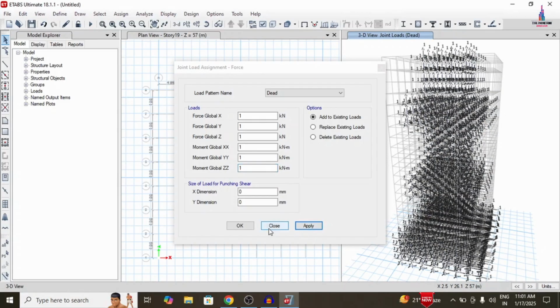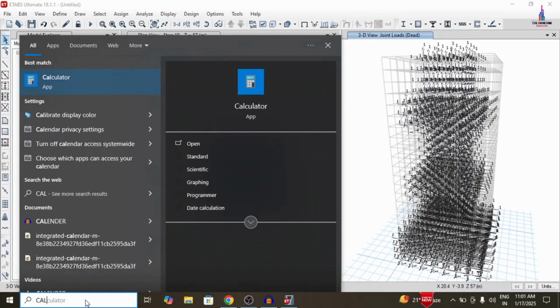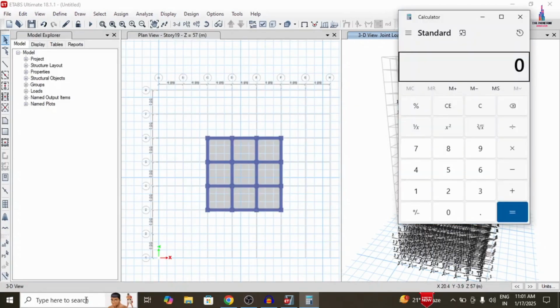Now after this we have to apply the wall loading condition system. Basically the wall load was calculated by using 3 types. One is external wall, one is internal wall and third one is related to parapet wall. So for the external wall we have to consider thickness is 0.23 multiplied by height of each wall with the unit weight of the brickwork, so that it will give the value as 13.8. Again for the internal wall 0.125 multiplied by 3 multiplied by 20, so that it will get the value 7.5. Again for the parapet wall load 0.125 multiplied by 1.2 meter multiplied by